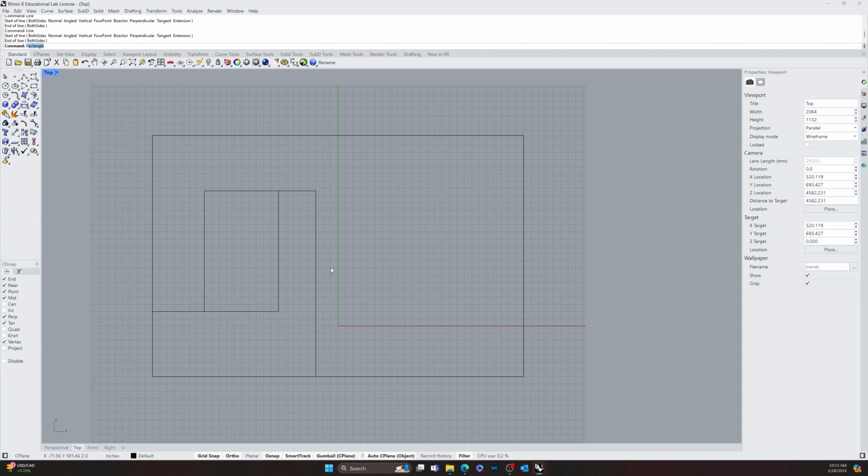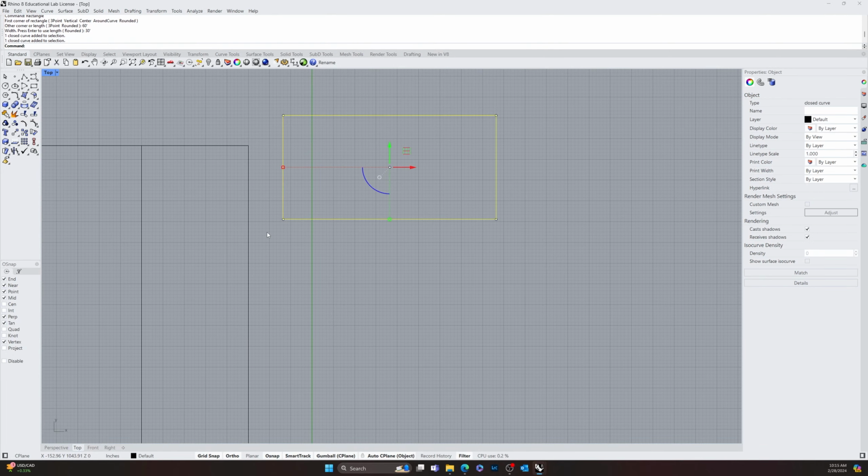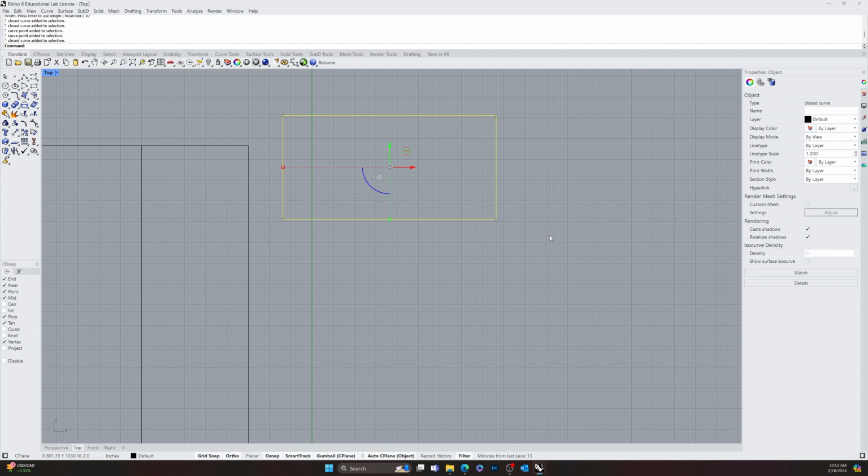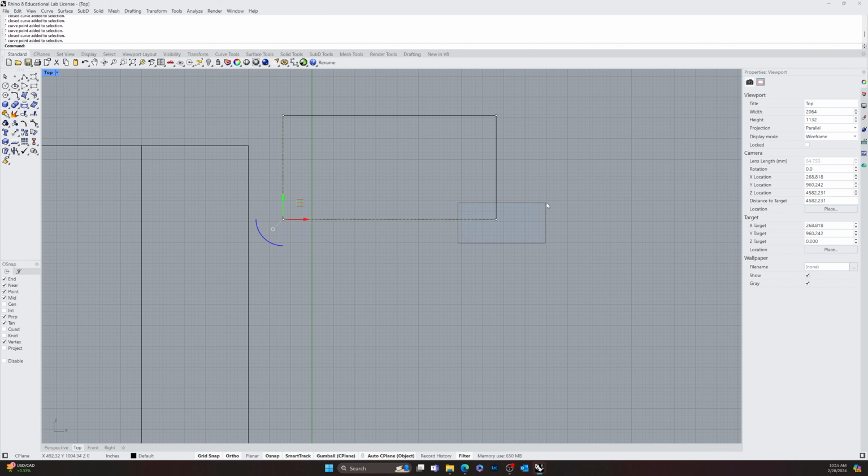So let's draw another rectangle. This one is going to be 60 feet by, let's do 30 feet. Maybe 40 feet. So I can always change these too. I can just left to right select on it, and when I click on it, it brings up the little points on it. And if I left to right select on this and then shift left to right select on this, I can just grab the gumball here and click on it and go negative 10 feet because the arrow is pointing up. I got to go the opposite direction and it moves it down.